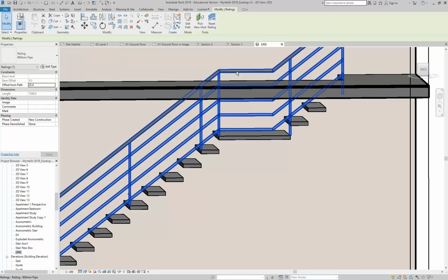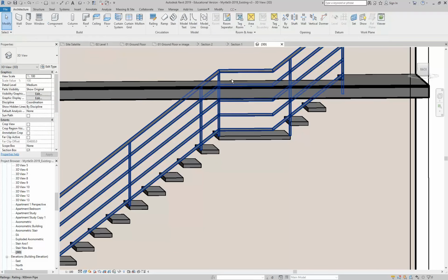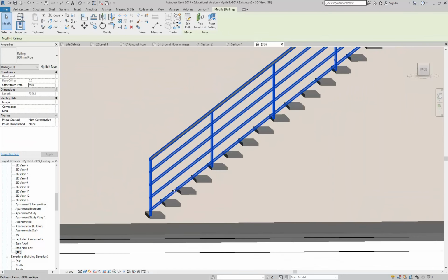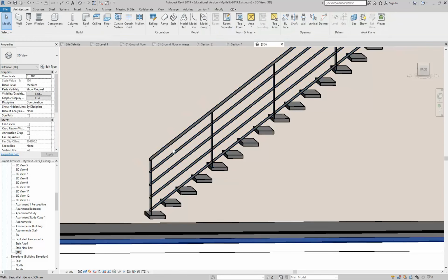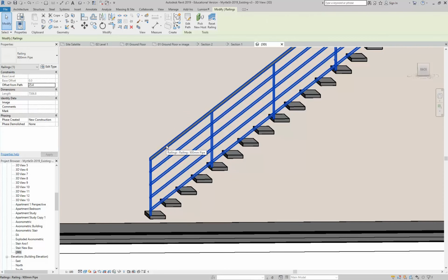So the question is, what's the minimum height that you need before you have to have a balustrade? It's 1 metre. So once the floor level or the change in level is more than 1 metre, then you've got to have a balustrade. And that's why you'll see a lot of stairs, they'll stop the balustrade a few steps before the end, because then the end of it is less than 1 metre above the floor, and so you can have that open, and that's kind of a nice thing. But the problem with that now is that you've got to have a handrail on one side of your stair all the way along, and that's a requirement now.